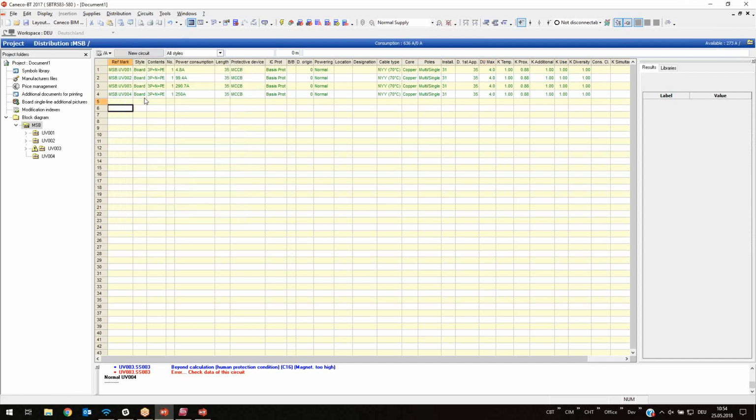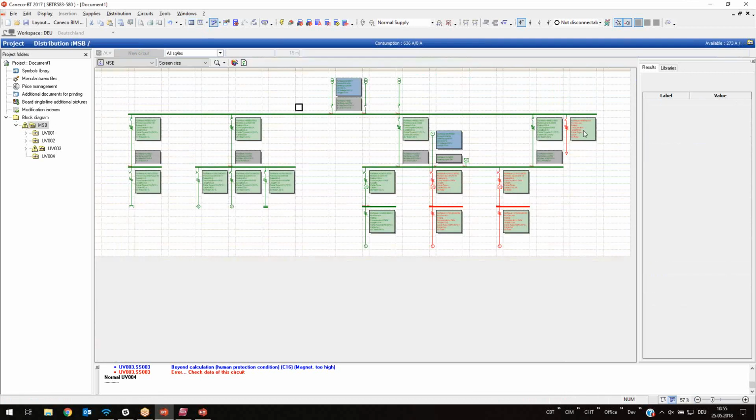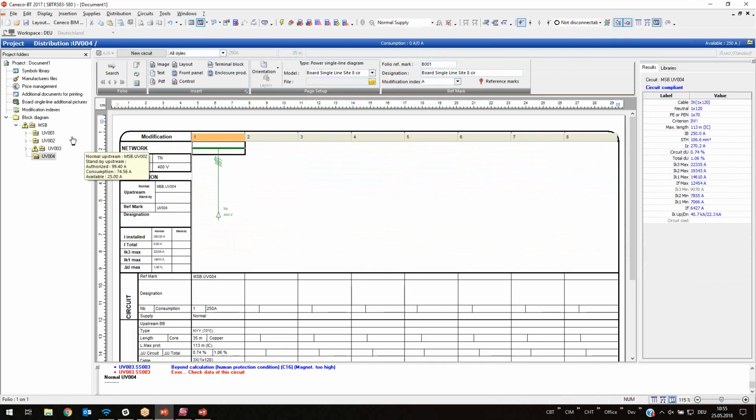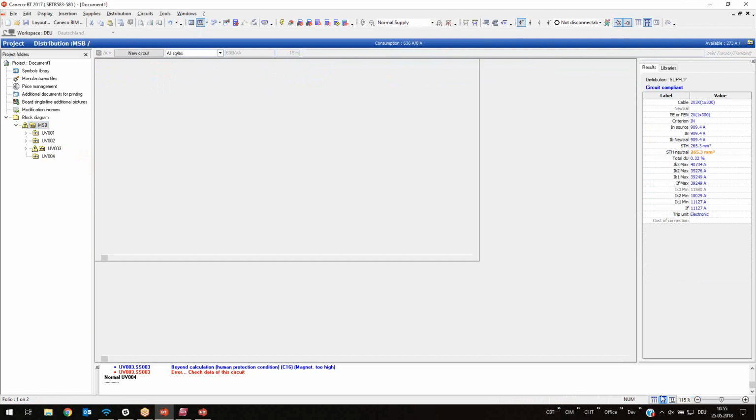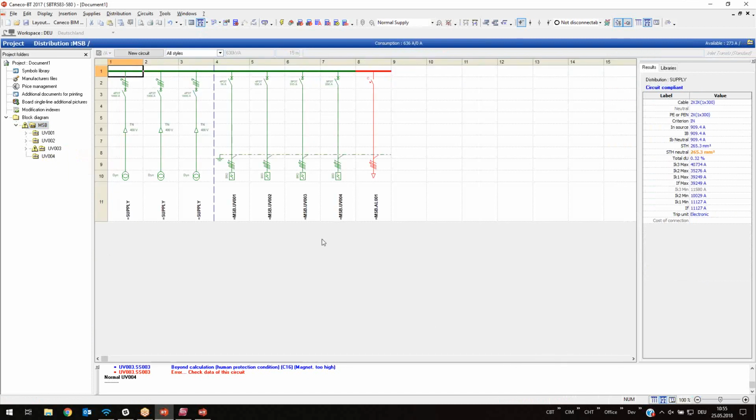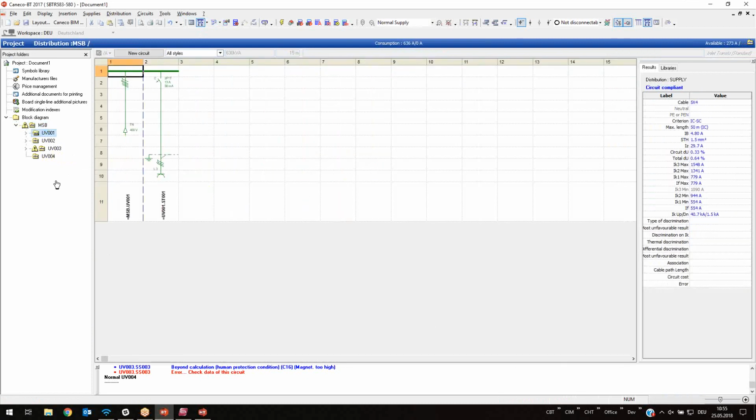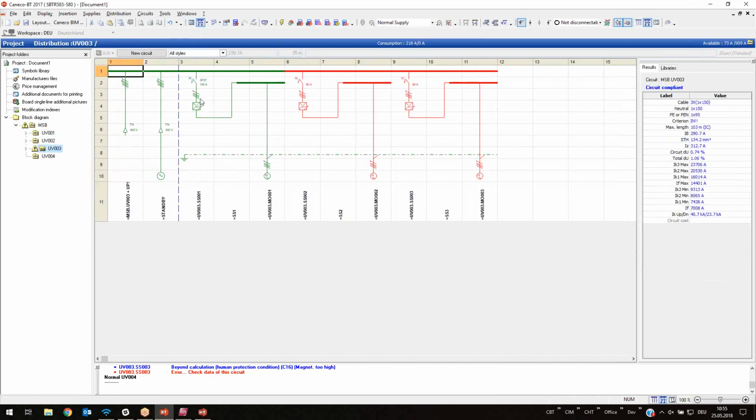Here you also can insert new circuits. You can work only in this view if you prefer. And if I change something in the table, I would have the same circuit also here in this view. The third possibility is to use the distribution board view. So you have a network schematic like this one, also automatically created, here with our frequency drives and the motors.